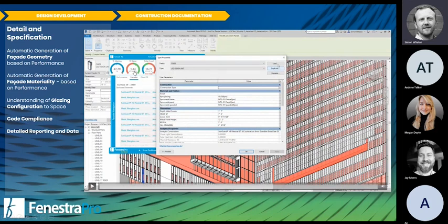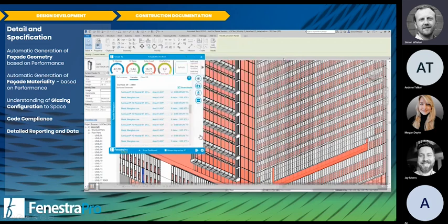And that goes in a hierarchy. So I can look at the whole building, or I can look at overall facades, or I can drill into individual spaces and surfaces. And every time I select something, my dashboards update, my charts update accordingly to give me an understanding of these things. But all of the materiality and some of those decisions that I'm making is written back to the Revit environment as well. So for example, that Guardian SunGuard neutral 67 is being applied to my glass families with the appropriate VLT and solar heat gain coefficient and R values, etc. But I can start changing those selections.